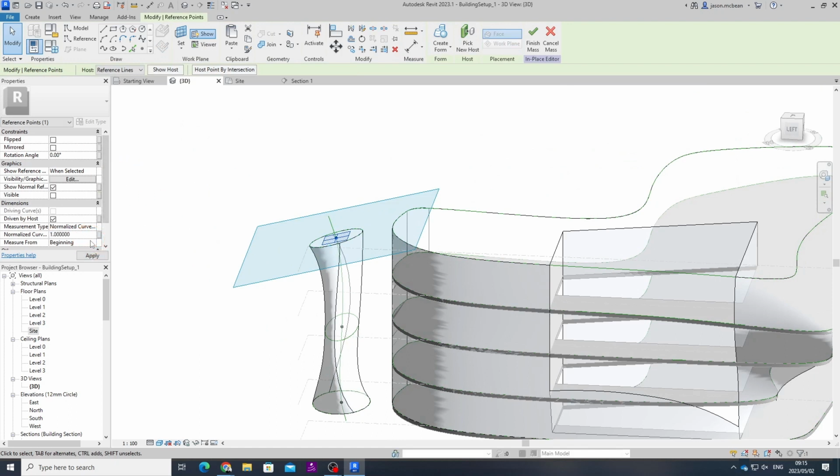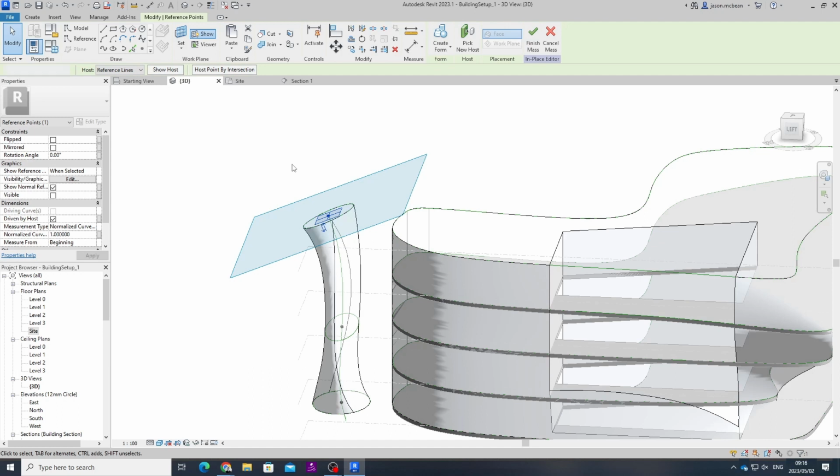So make this 1, it'll go right to the end. So you can actually make a form, and you can use Dynamo and do procedural modeling. So as the sun moves, these shapes can also dynamically change. Okay, it's very powerful, but it does come with some caveats.